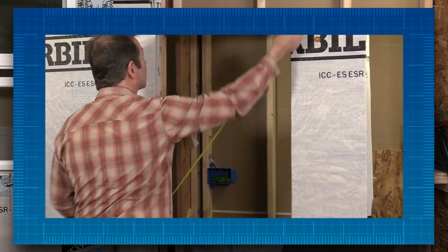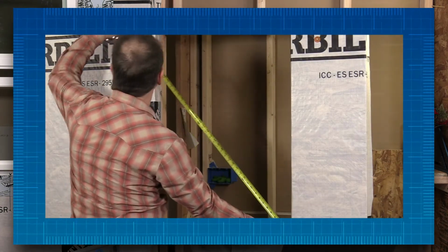When we come to our squareness of that window, this helps too. If our window's out of square, it doesn't matter if it's oversized. It needs to be the same shape as the window. Windows are made square. The rough opening has to be square. We can check that in a number of ways. We can measure our diagonals. Those should be equal. That will tell us that that rough opening is square. If it's a small enough rough opening, we could use a framing square to check those 90-degree corners.